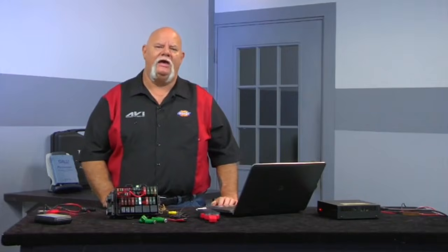Let's say we have a front-wheel drive automatic transmission vehicle that is setting a 2-3 shift solenoid trouble code. Now, to get to the shift solenoid pack, the transmission cover has to be removed. It's a front-wheel drive vehicle, and this is going to require 6 hours labor. However, if I can get to the power feed wire to the solenoid pack in the transmission and get my